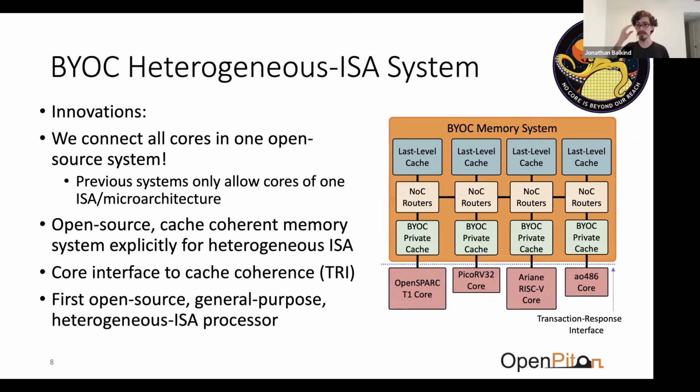And this was really like an extension to OpenPiton, an improvement to PMesh, a new version of PMesh in some sense. And the reason that you might want to build this, in terms of an end user's needs, is that you might have a particular application or a particular design need that can only be met if you bring together cores of different ISAs. So maybe you are in need of the most performance you can get, and you want to really squeeze that, or the energy efficiency. But there are other needs.